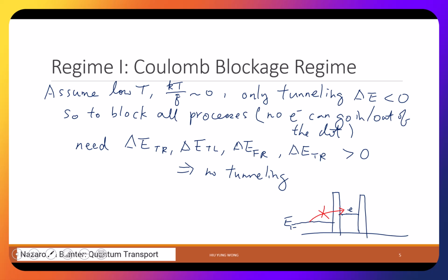We don't have an extra gate to control this barrier. We have a very tiny capacitance, so we have a very big discretization in the energy. And through tunneling, we can control it one by one. This has nothing to do with the spin qubit. I think you're thinking these are the plunger gates, these are the barrier gates, but that's not the case.